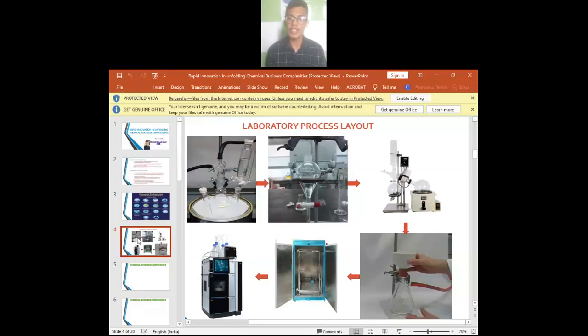I mean substances soluble in solvent. Organic layer is separated from the aqueous layer and washed by brine solution, that is sodium chloride concentrated in water. Organic layer is then distilled by heating at a solvent's boiling point through rotary evaporator in case of laboratories, or through distillation columns in case of production plant.